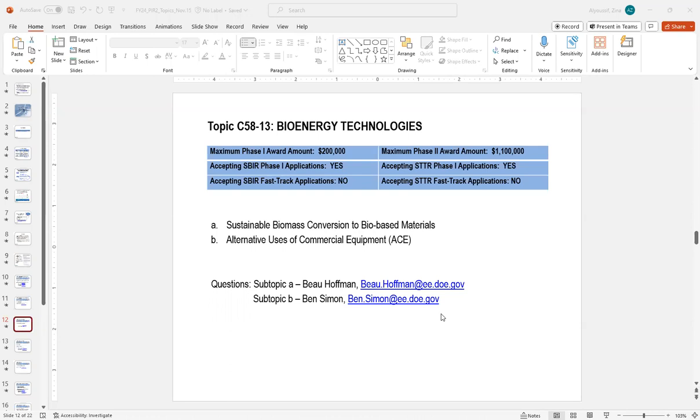The feedstocks of interest for this topic include energy crops, cellulosic materials such as agricultural residues, organic wet waste such as food waste or sewer sludge, algae, construction and demolition debris, and oil seeds. Woody biomass like sawmill debris or forest thinnings and other non-biomass based feedstocks are not of interest for this topic due to their mature industries. Targeted pre-processing metrics could include, but are not limited to, size reduction, particle size distribution, contaminant removal such as inorganics, reducing the moisture content, densification and extraction of oils, starches, etc.